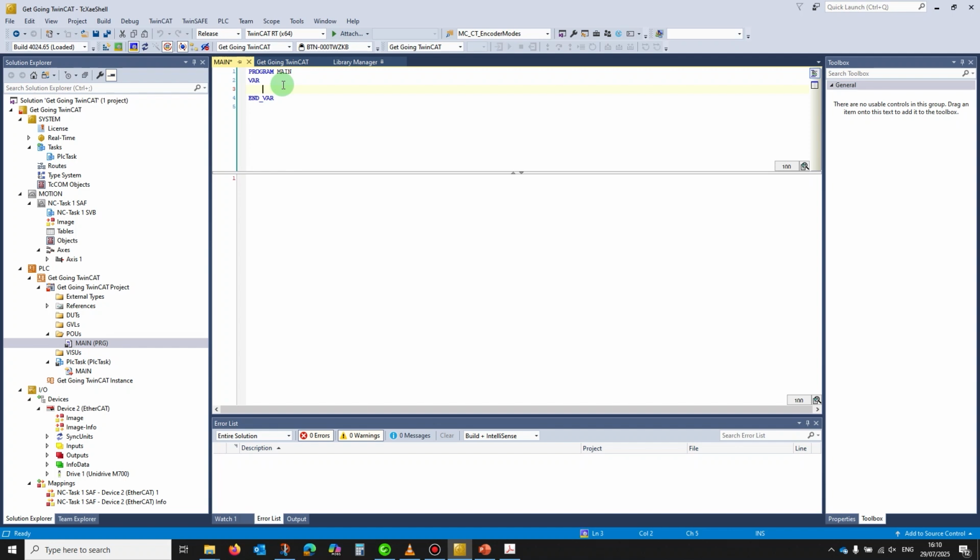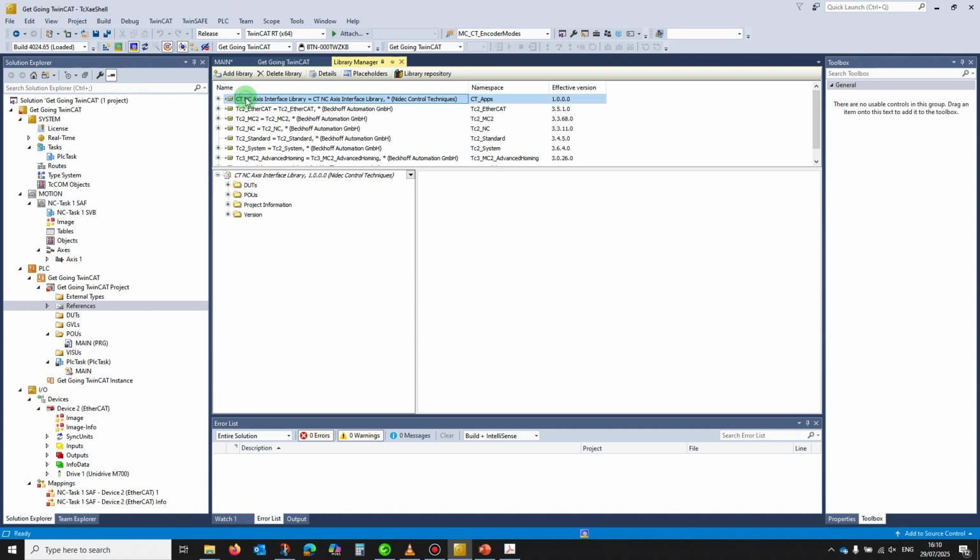All we've done is put a wrapper around it to make it quicker and easier to get going, because if you're using PLCopen you will find that it's just a box of individual parts that you've got to go and connect up. So what we've done is some of the legwork for you. If I click on here and then go POUs, function blocks, and motion interface, you can see there are in fact 4 of them.